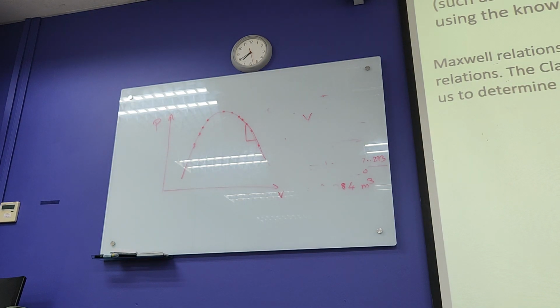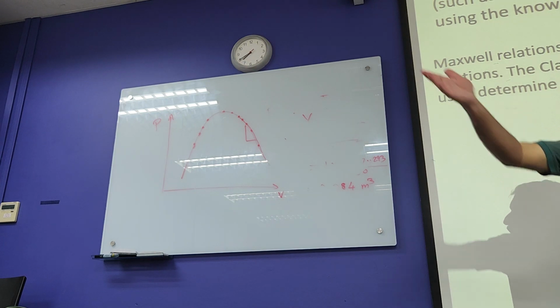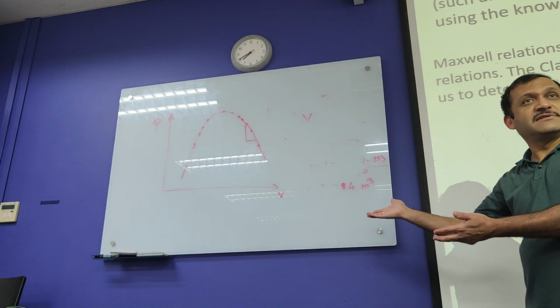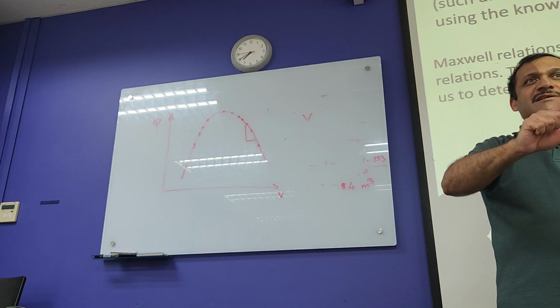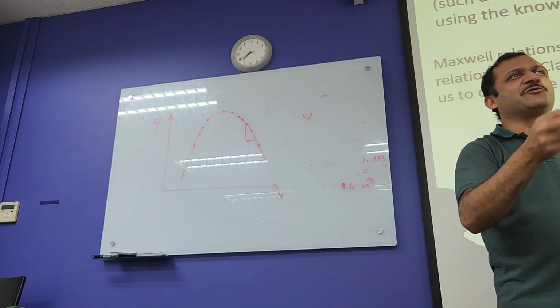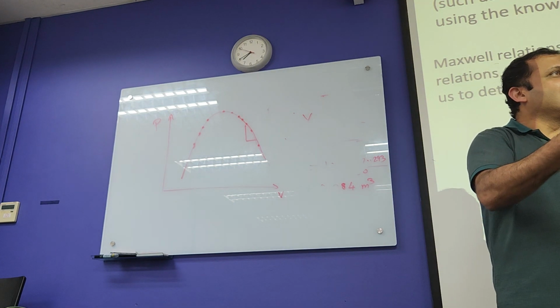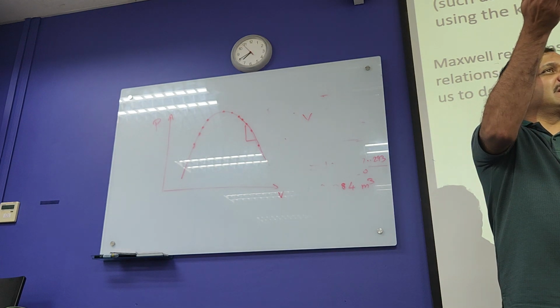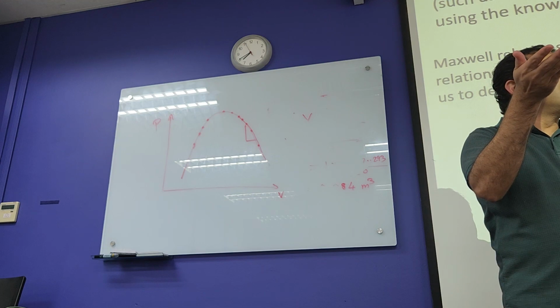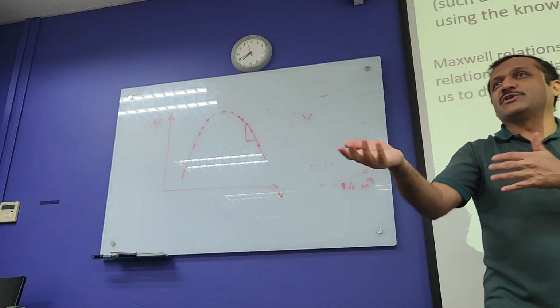Constant volume chamber: take a cylinder which is a rigid cylinder or tank, put some liquid in it, close it so that the volume is constant, start heating it up, measure temperature, measure pressure. You get a pressure-temperature curve. Then you get a piston cylinder device with almost no friction, repeat the process, add some liquid, heat it up, measure volume, how much the piston is rising, that gives you the volume change, and how much is the temperature change. That gives you the slope for temperature, volume.